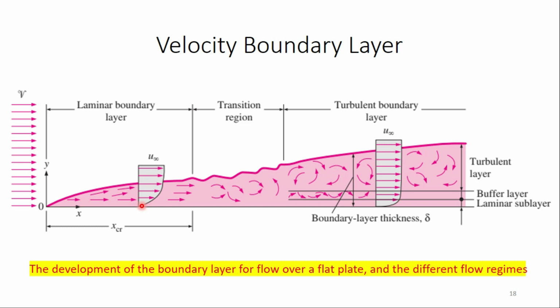So this is the velocity profile. At this point where my pointer is, the velocity is 0, while slightly away from the surface in the y direction the fluid will have some velocity. It will face some friction due to this flat plate. When we move slightly away from the surface, the velocity of the fluid layer will be slightly higher, and if we move slightly further away, it will be higher again, because the fluid layers away from the surface experience less friction. At some point, the fluid layer far away from the surface will have the maximum velocity, and it is known as the free stream velocity.